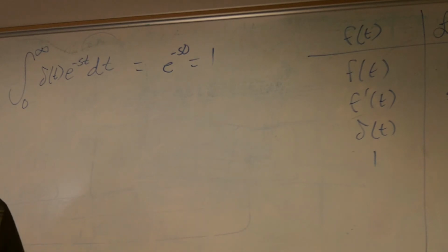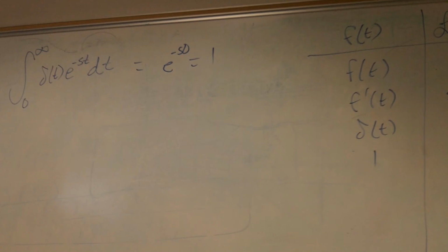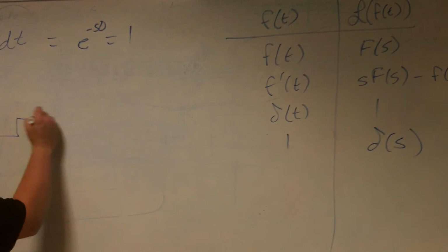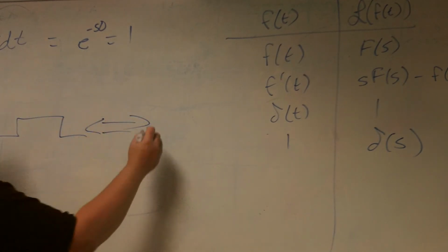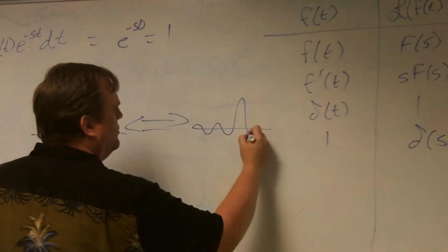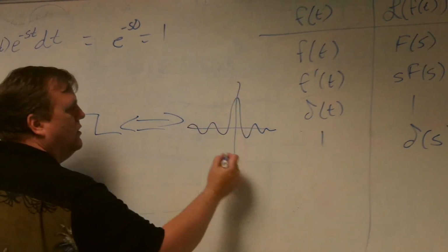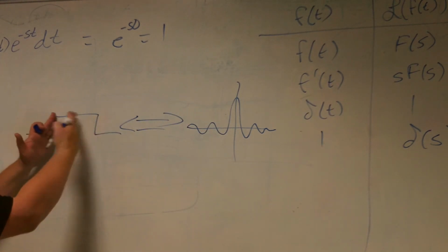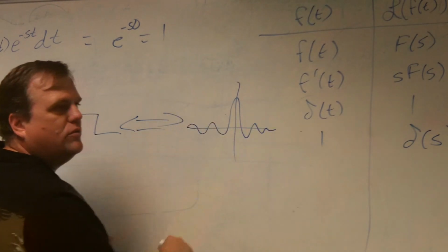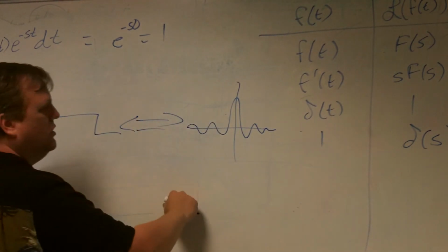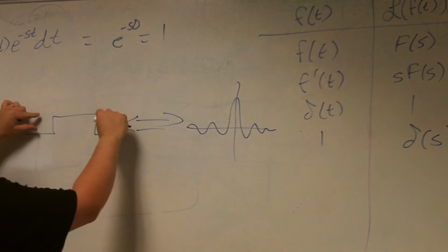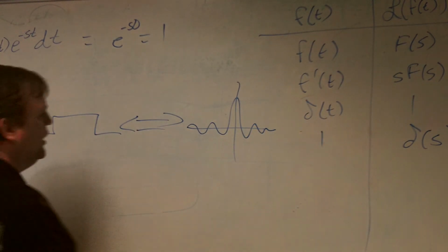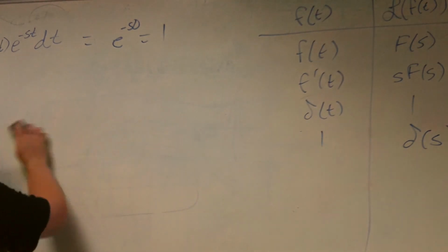And there's in-betweens on there, and it's got all kinds of fun stuff, but I'm not going to go through that. There's a square function, and it goes to a sinc function. So if you have a rect, it's going to transform to sinc. And this distribution carries off, but it's damping down. The tighter you get this, the more that spike comes up and these damp off. And the wider this one goes, the more that goes up. The tighter this one goes, the more it spreads and becomes 1. So you can get them either way. That's kind of a big thing often.